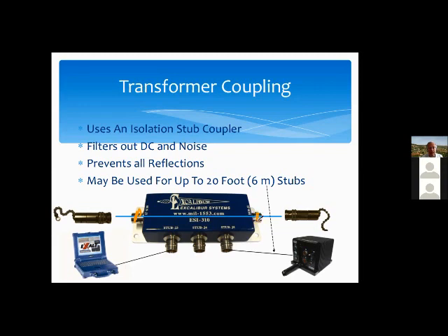If you look at the writing on the box itself, here it says bus J2. Here it says bus J1. Whereas these three guys are called stub J3, stub J4, and stub J5. Now they look the same. And so you can connect your 1553 cable, which is a twin-X connector. In theory, you could connect it from here to any of these 5 connectors. Physically, you could, but you shouldn't.